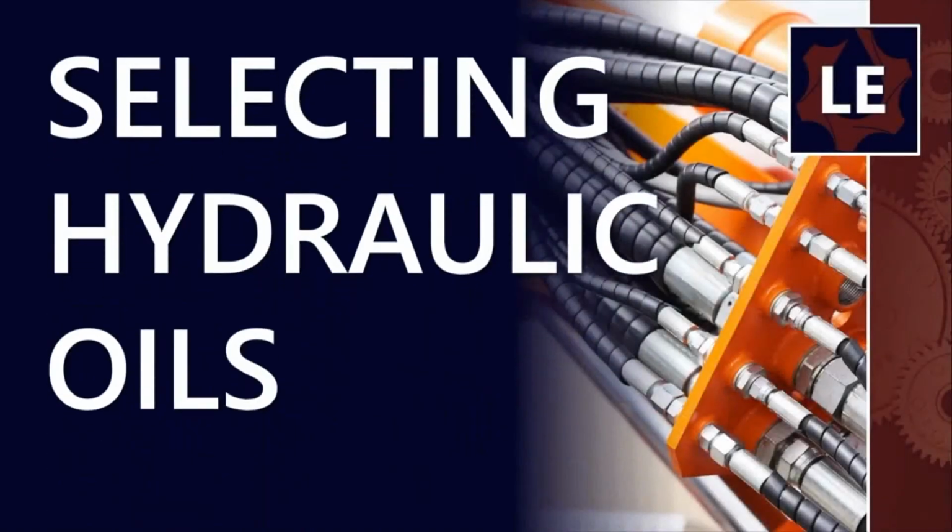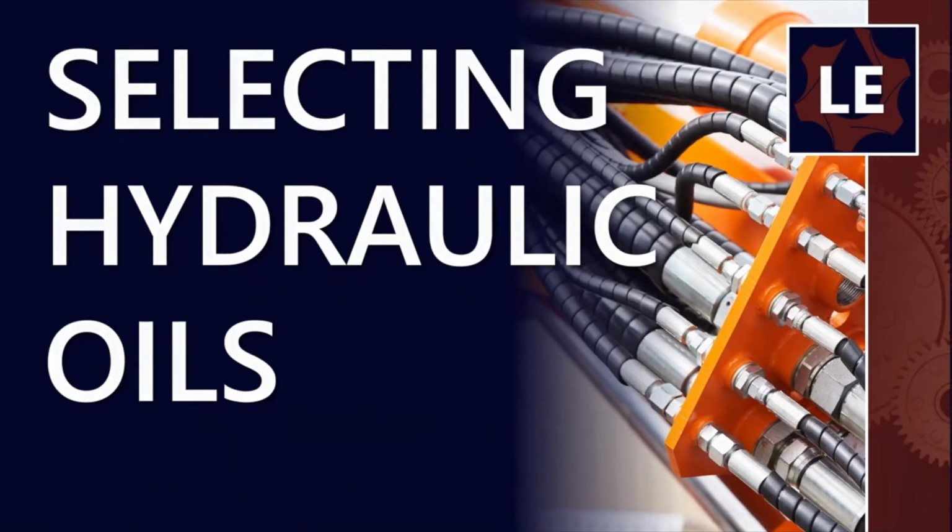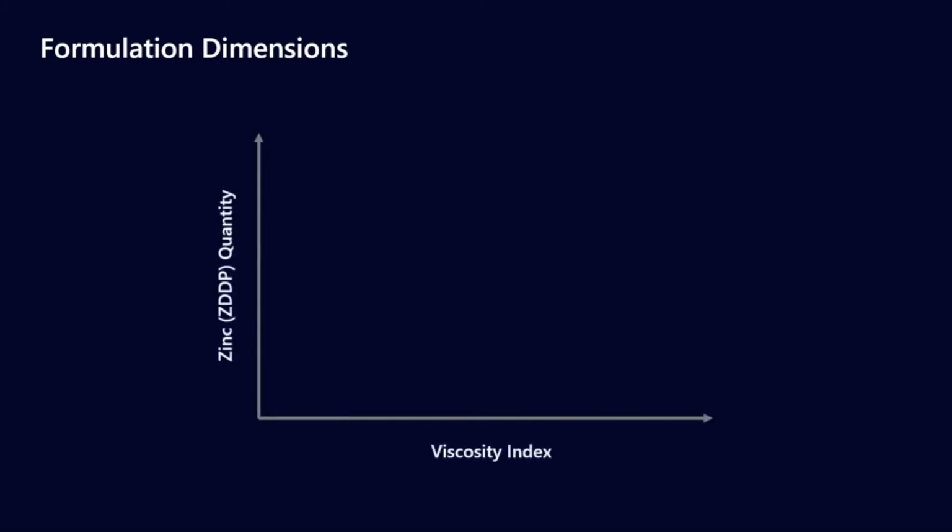In this video, we're going to talk about how to select a hydraulic oil for your application. So, one of the easiest ways to think of all the different hydraulic oils is in the way that formulators think of them when they formulate the different products. Two of the major ways that they do that is to look at two of the formulation dimensions, which would be the quantity of zinc in the formulation as well as the viscosity index.